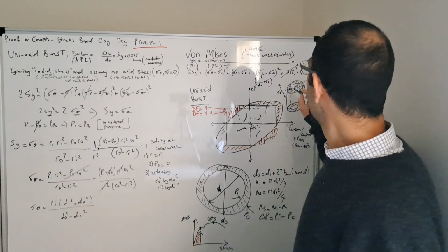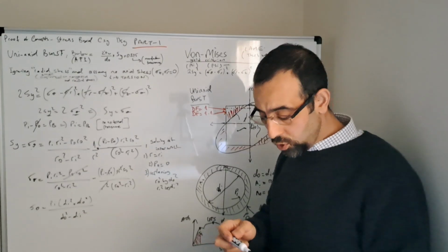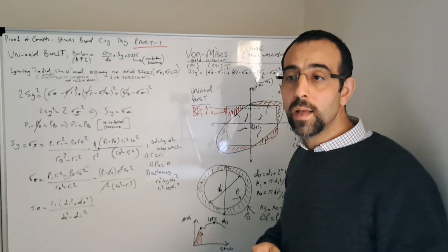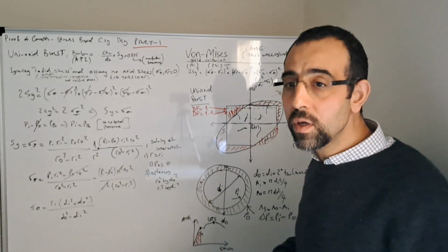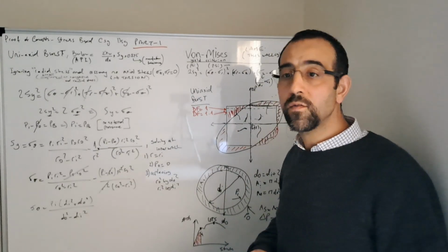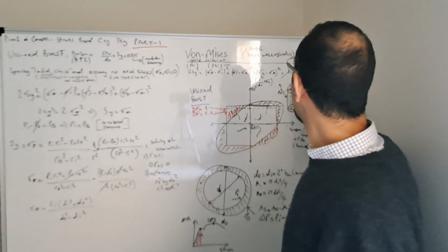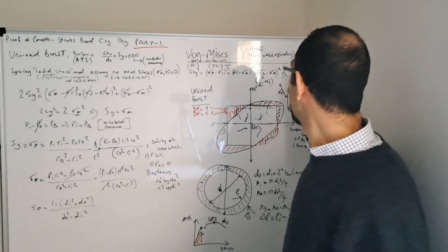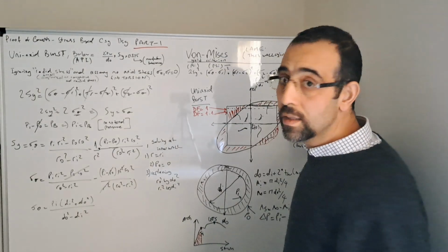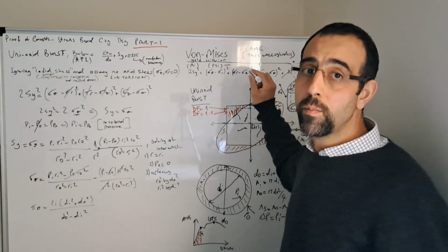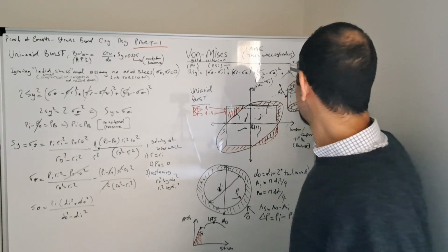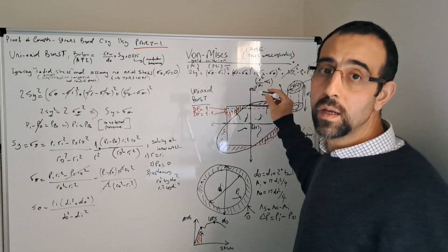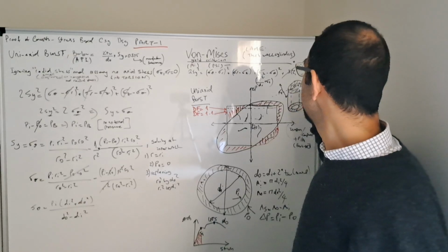So when we look at this equation, if no torsion is initiated, i.e. if we are not rotating the pipe for cementing, or let's look at the ERD case where you need to get the liners into the horizontal section, so you need to rotate to break the friction. Other than that, you will have no torsion induced. That's why we neglect this torsion term, and it applies to many cases where there is no torsion. So it's zero.